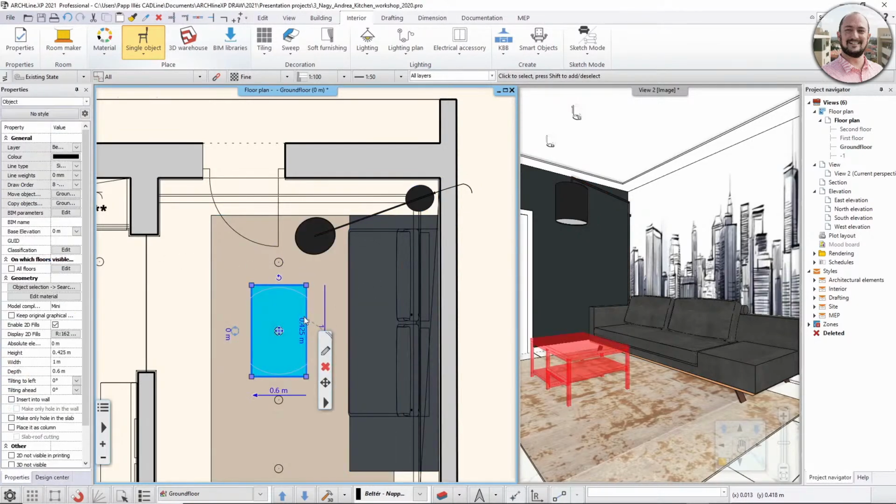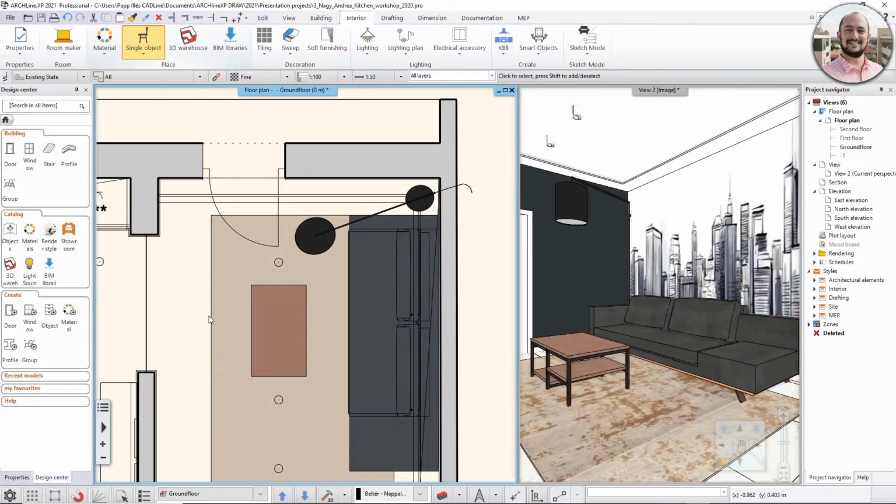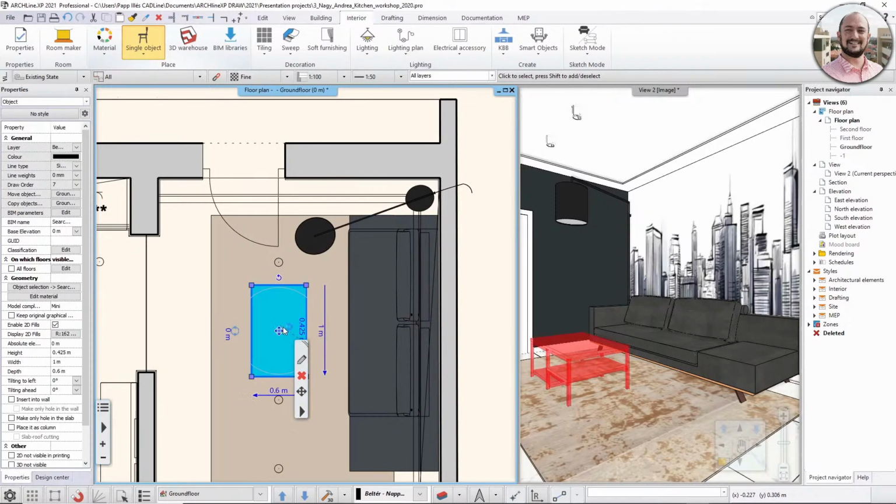And also here, just to make sure that whenever I change this, it won't fall under this other item, I will just simply go there and say that the 2D fill is enabled, and then the draw order should be at least number 7 above bottommost. Now in case I do that, there might be another issue with the other unfilled objects as well, like these here, that they overlap, because simply the same thing happens with all the rest of the objects.